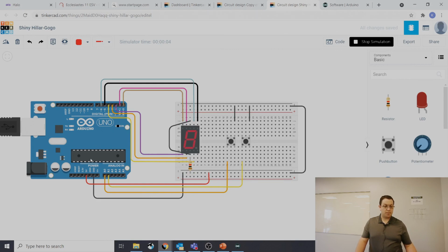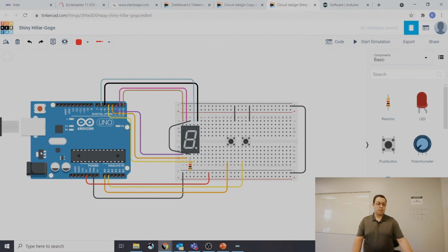So it's not going to catch all the possibilities. But if it's like this, and you have power and ground in the same line, you're going to have a short, and it will heat up the Arduino, and you can actually damage the board itself. So if you don't have the on light illuminated, unplug it and double check for a short, and make sure that things are taken care of.